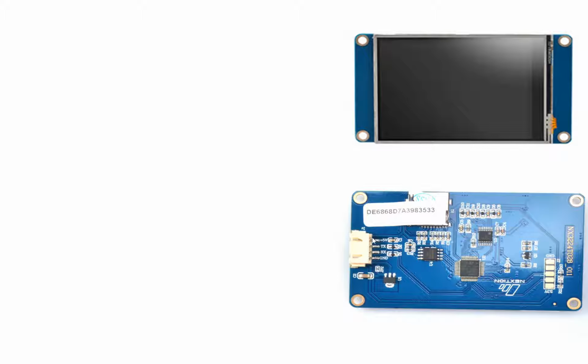Now let me show you the labeling here. Although it is already mentioned here, the top one is the 5V pin, the second from the top is TX, the third from the top is RX, and the fourth pin from the top is the ground pin. So this shows that this is a UART based interface, but we cannot interface the Nextion touch screen directly with a PIC16F877A microcontroller. First of all, we will need to burn an interface, or you can say a touch display interface or a firmware, before we can continue with a PIC.